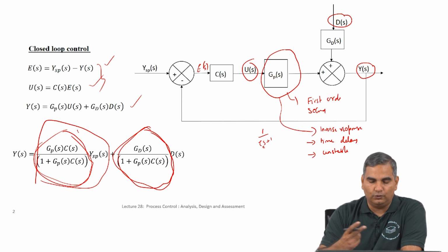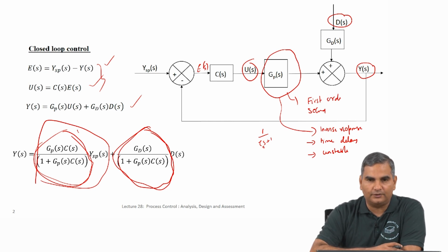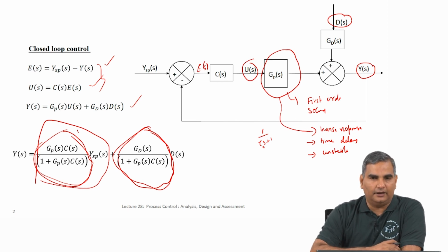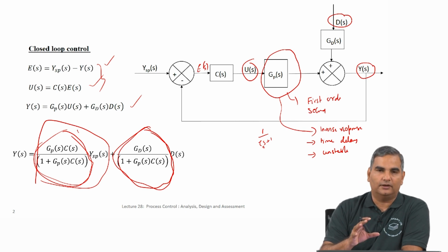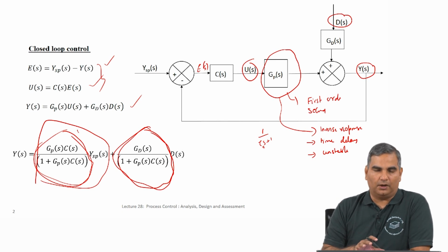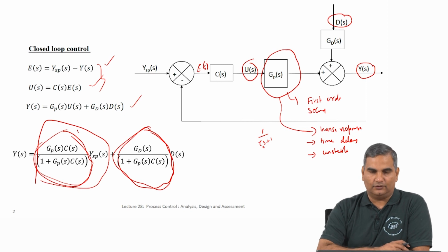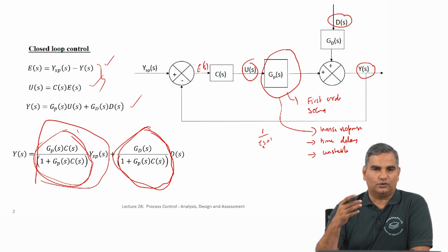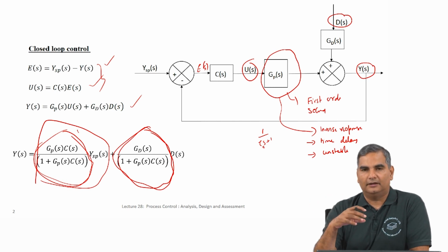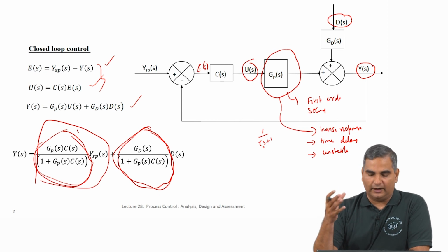loop, let us say to 2 variables at a time, 2 inputs and 2 outputs, and show you how one can generalize this idea of feed forward control to what is called decoupling control, and that idea I will explain with a 2 by 2 multivariable system. So, that will be the first time we will actually look at a 2 by 2 system in a block diagram form, more fleshed out block diagram form like this in this course, and you will see how this notion of feed forward control can be thought of as a forerunner for this decoupling controller,